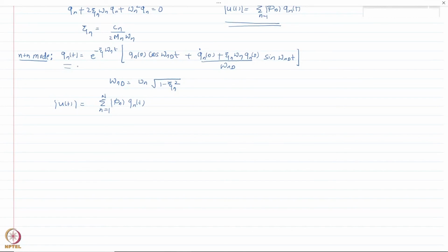Now if we notice in this case, typically we do not get the damping matrix. I've told you that you can get the damping matrix and see if it can be diagonalized or not. But in practice there is no way we could get the damping matrix by just considering damper elements in a structure.